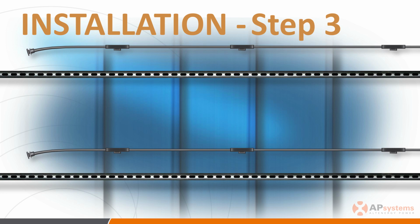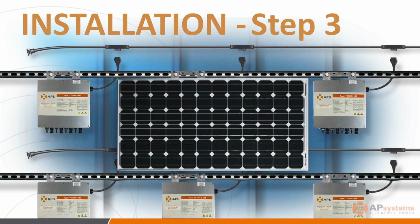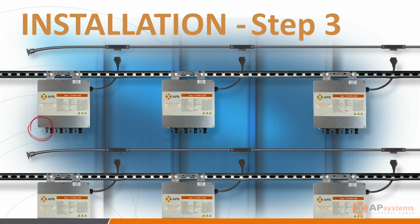Step 3. Attach the YC1000s to the racking system, remembering to account for panel orientation, portrait or landscape, and the fact that each inverter is going to be connected to multiple modules. Note, do not install the Zigbee antennas until after the inverters have been fully mounted to the racking system.